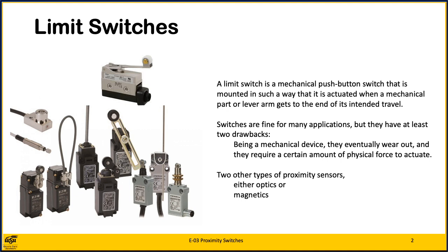Proximity refers to a transducer that can determine if something is in the proximity of the switch. Although technically also proximity switches, limit switches are colloquially called limit switches as opposed to optical and magnetic proximity switches that are called proximity switches or proxies.